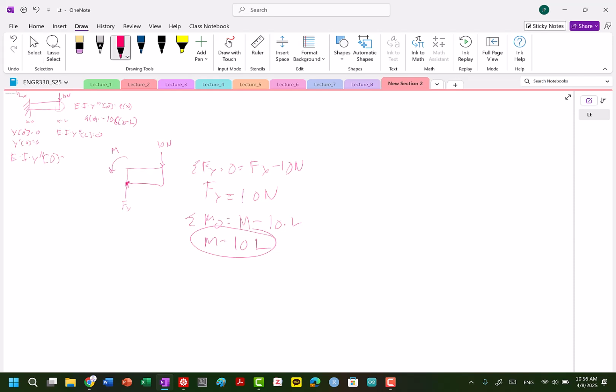So when I'm trying to find my bending moment at that origin, I need to draw my bending moment diagram. But really all I have to do is look at this. So I make my cut here. This is my V. There's going to be some M(x). We have this moment here, M. We have our F of y here. And you have the minus V. There we go. So let's calculate what the moment's going to be.